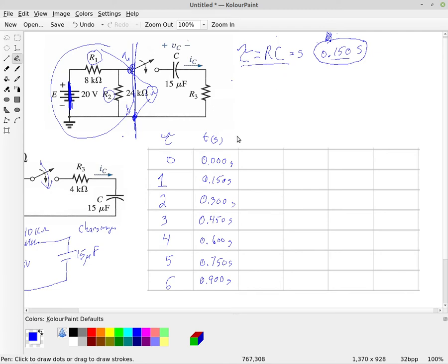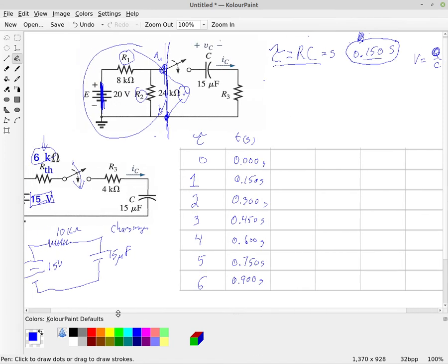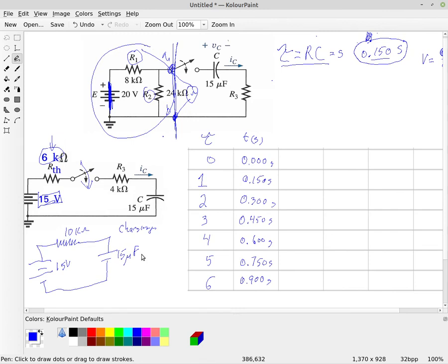And so the capacitor is uncharged, and what that means is that there's no voltage on it, because remember that the voltage on a capacitor is equal to the charge divided by the capacitance. And since there is no charge, the voltage must be equal to 0. So if we know that the capacitor has been discharged, we know that there's no voltage on it, then looking at this circuit, we know that there's 0 volts across the capacitor.